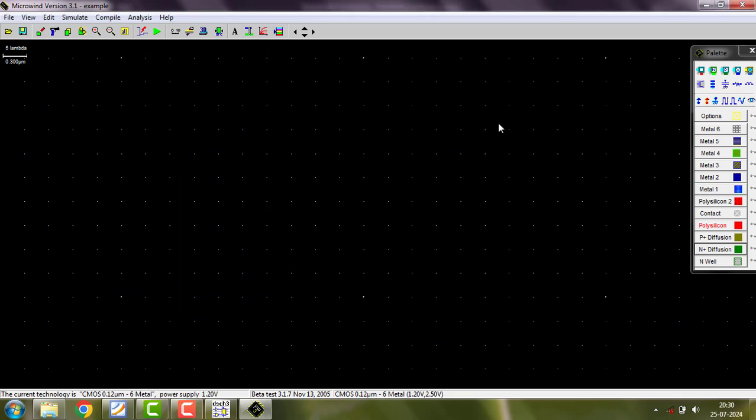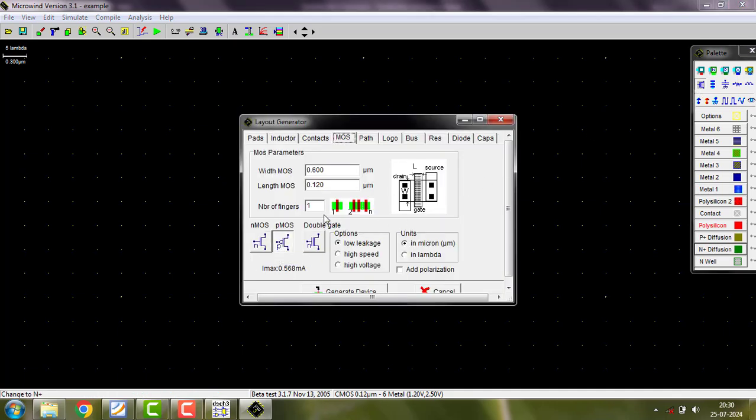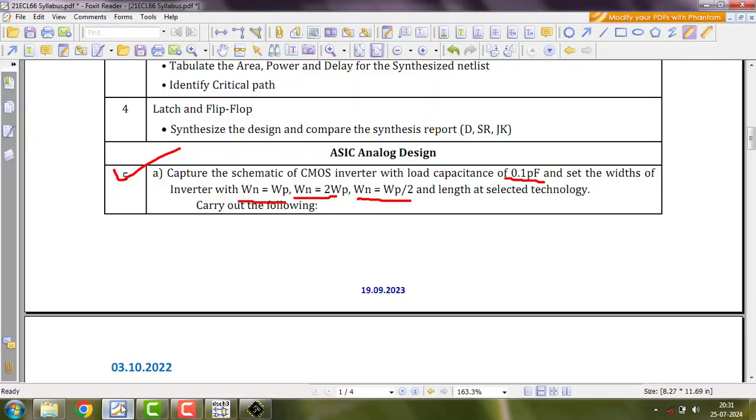Okay, now let's go ahead and take PMOS. Minimum is 0.6 micron. So what I do, I'll check for this as well. So what is the minimum? 0.6. Keep that in mind. 0.6 micron is minimum for N and P. So what is the minimum of WN? In this case it is half of this. What is minimum of WP? So 0.6, which is not possible.